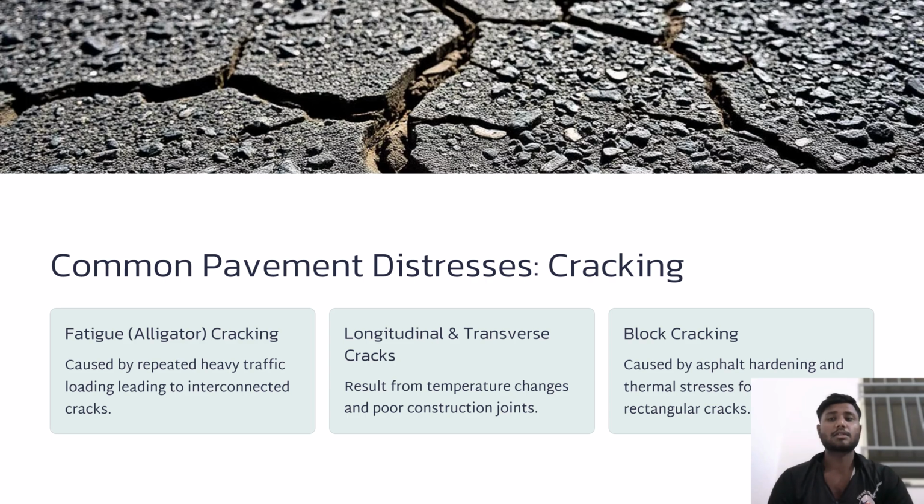These cracks happen as a result of temperature changes and poor construction joints. Third one is block cracking, caused by asphalt hardening and thermal stresses, forming rectangular cracks.